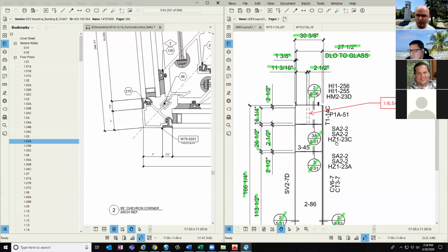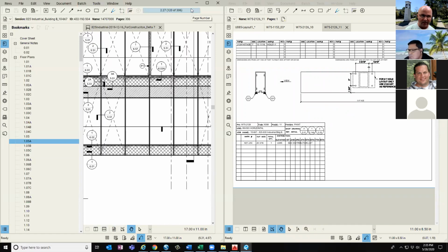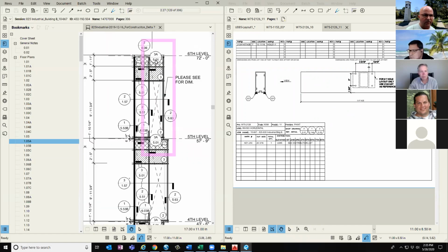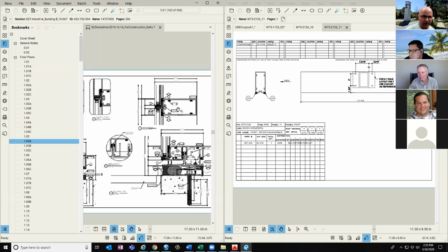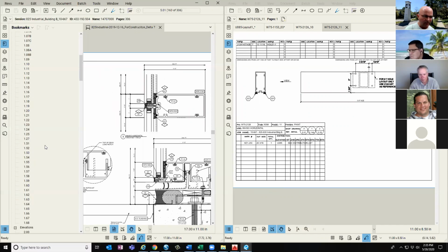Now when I go up to my next horizontal, I've got the horizontal that has the pony tube attached on the top of it. So let's take a look at that on the shop drawings to make sure that makes sense. When I go to this detail, this is going to be my 3A on 501. Well, I have the horizontal cut here, but I'm not seeing what's happening on that pony tube again. So if I want to reference the pony tube specifically, I need to go back to see what's happening on that 565A detail that we had penciled in previously.